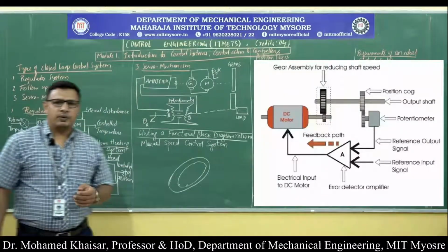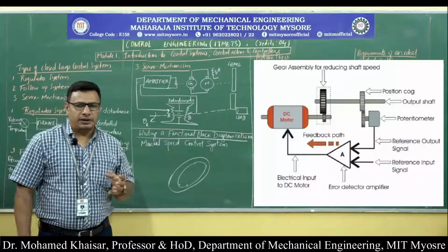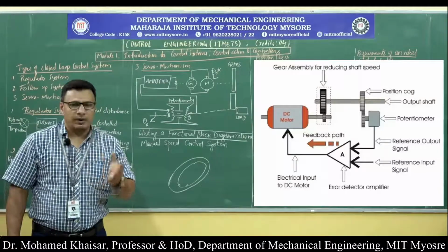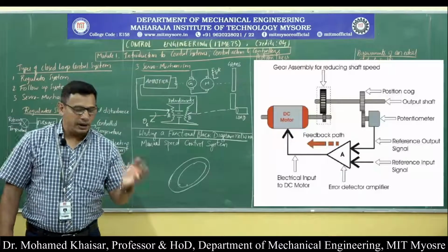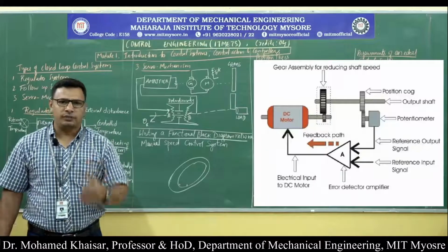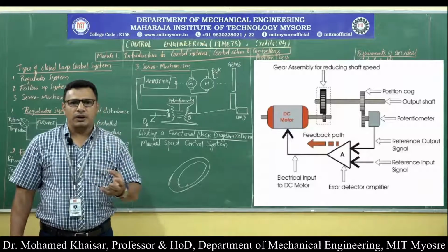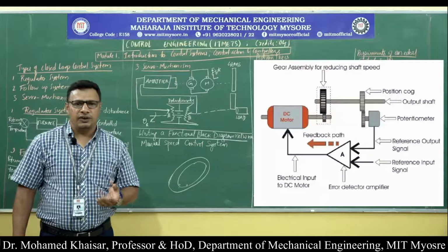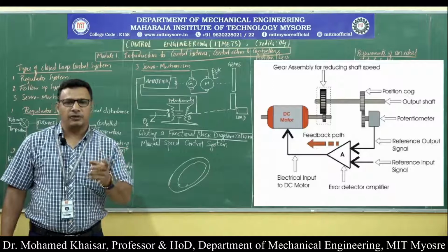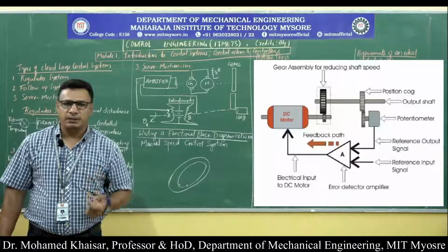Servo mechanism is a kind of closed loop control system wherein the controlled variable will be the mechanical position. Say some component has to turn, once I apply the load, by say 30 degree, 40 degree. So the change in the mechanical position could be the controlled variable you want from the system. Or you can also want some time derivative outputs, such as after applying the force, the speed of rotation must be so and so, the velocity or the acceleration, that may be the output.